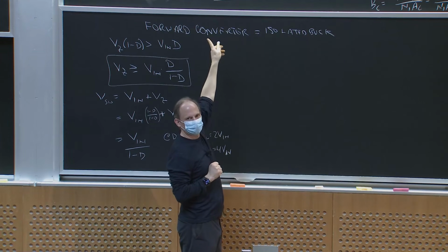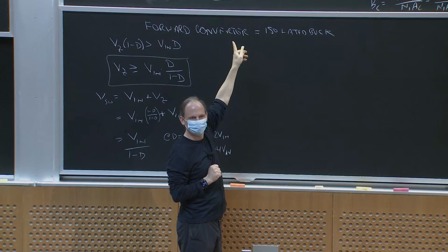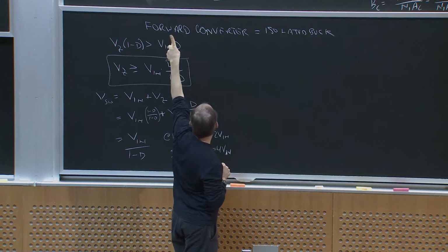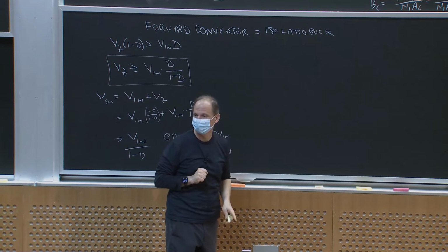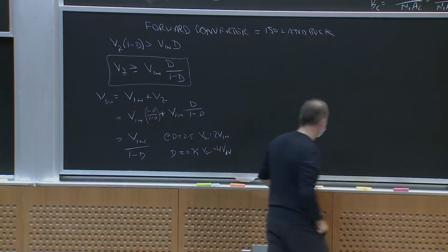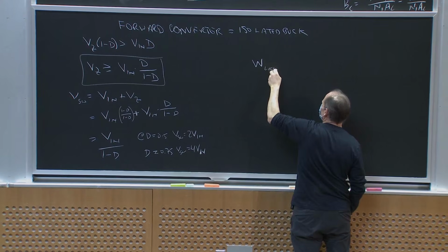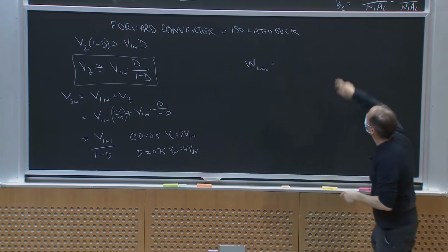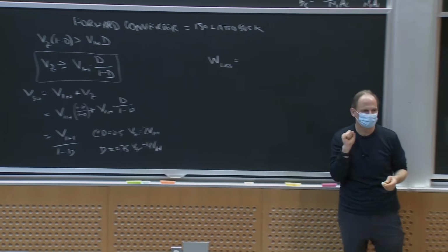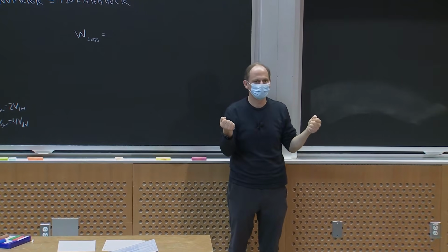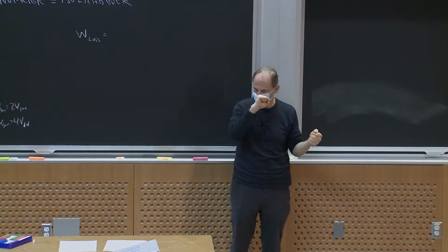I dump it into a Zener diode. I throw it away, right? So I hate throwing away energy, but this circuit, that orange circuit is throwing away energy, right? Well, how much energy do I dissipate? And by the way, this process of driving the magnetizing current back to zero is called resetting the core. Okay, how much energy do I lose in resetting the core back to zero